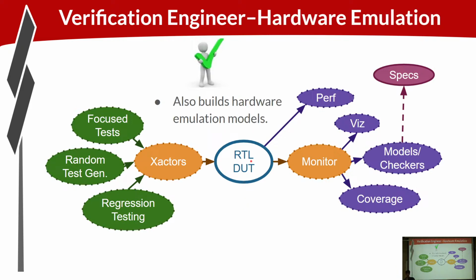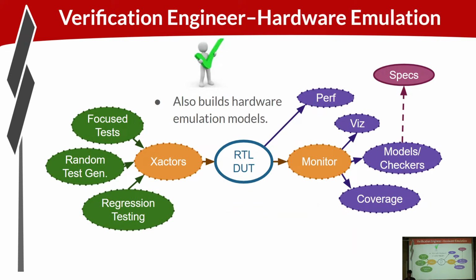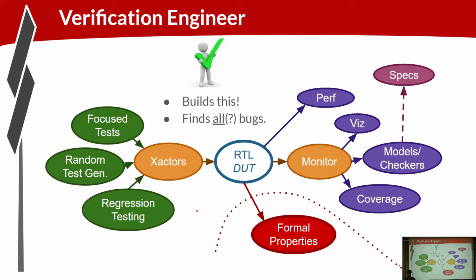When you're doing hardware emulation, you're really trying to hit those deep simulation cases. So it might take days of simulation to get through just hardware reset alone on a full chip system. So you might use the hardware emulation platform to do the reset sequence. You might use it to do Linux boot, for example. And you can't afford to have the same level of software running in that ecosystem as you can in simulation, when your simulation runs are shorter.